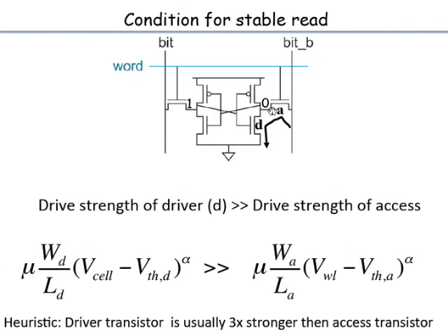You will have some subthreshold leakage here through this cell. So now imagine you are reading this cell, but all the other cells in the column have opposite data stored in them. Then even though this cell is not pulling a current, all the remaining 127, 255, however many you have, will start pulling current from that cell.